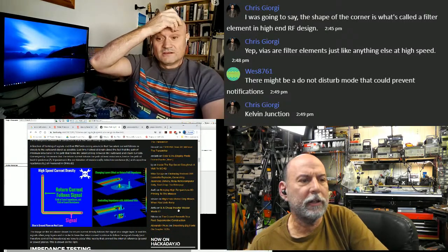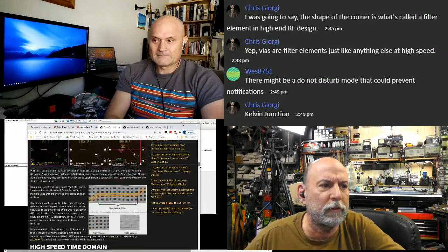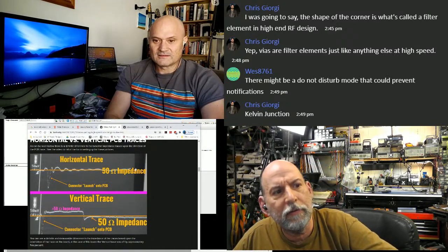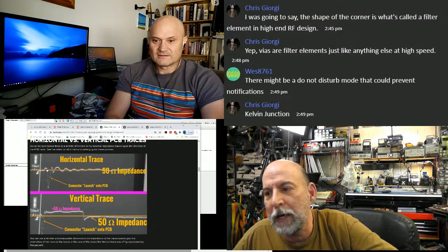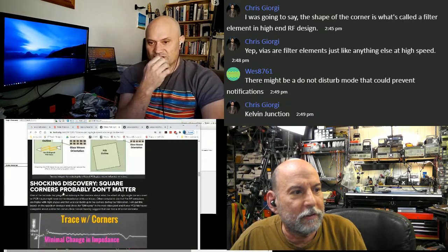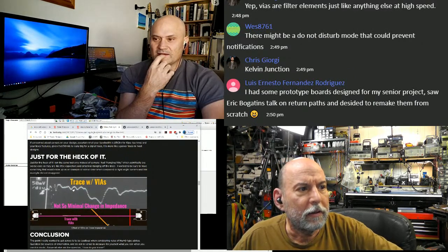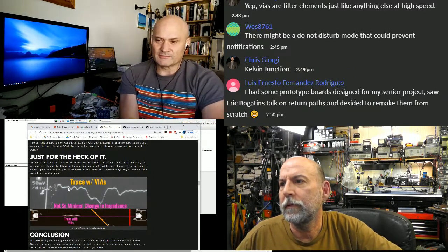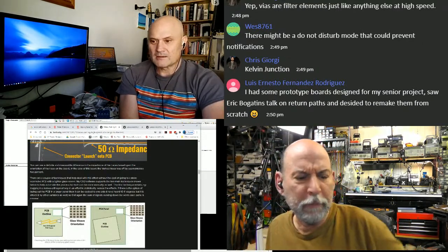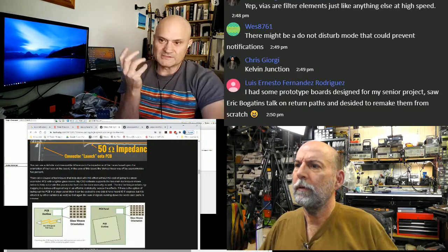So Chris had actually, I think it was him, asked about what resolution we could see on an RG cable. I'll tell you that this top trace right here is only 6 inches of a PC board, and I'm seeing about 1/10 of an inch, if not smaller. Right, so on RG8, the velocity of propagation... It'll be muddier. I don't recall, but the RG8 cables are probably a faster velocity of propagation. They've got a velocity factor of about 0.7, is my memory. Yeah, because the dielectric in them is mostly air, usually.